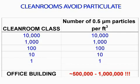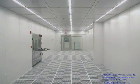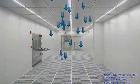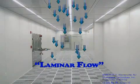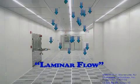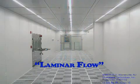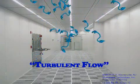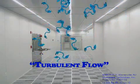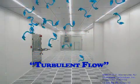The only way to control particulate contamination is to control the total environment by a combination of filtration and proper use of materials. Cleanrooms are designed to achieve and maintain airflow with a uniform velocity along parallel flow lines, extending from the ceiling to the floor. This type of airflow is called laminar flow. The more restriction of airflow, the more turbulence, and this turbulence leads to lateral particle movement, which may cause particles to accumulate onto surfaces.